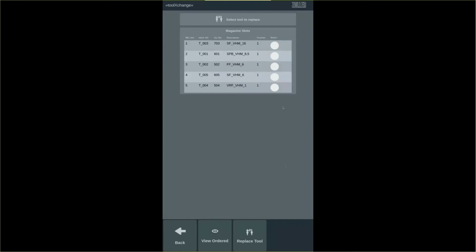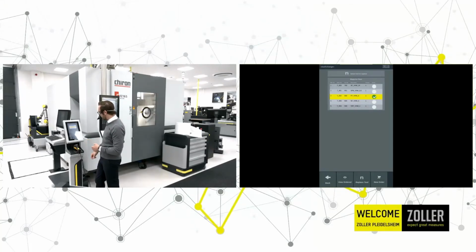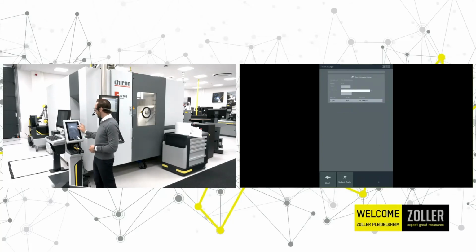So tool exchange means I see here my magazine, so all the tools which are on my CNC machine, and I would like to replace this tool. I cannot scan it because the tool is physically in the magazine. So I hit only the tool which I want to replace, and I say, okay, new order.